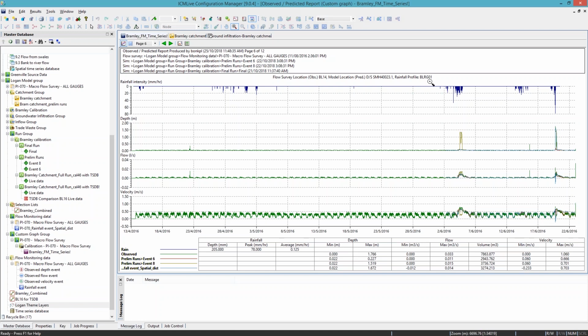If computational requirements are too much, you can break it down to single event simulations if you start using hot start files, and InfoWorks does let you do that. But even then, obviously the hot start file you've run doesn't take account of the changes you might have made as part of the calibration process. So you really should be running a full period simulation pretty regularly.